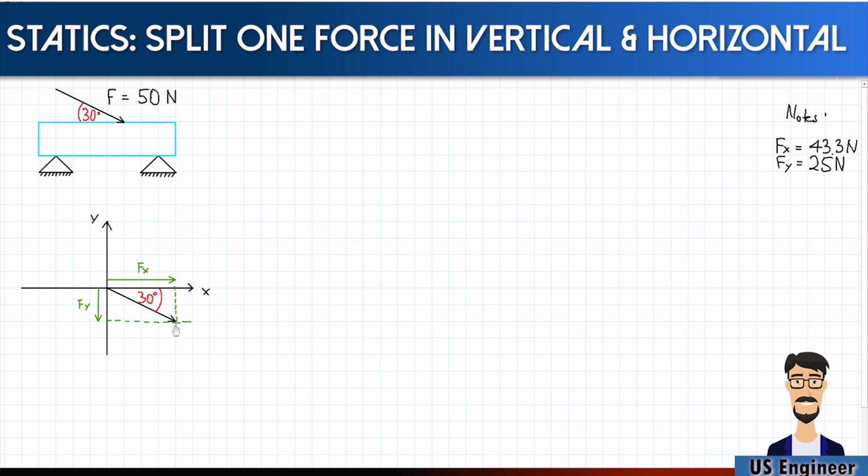Now, as I said before, there is a geometric and a mathematical approach to computing the magnitudes of the force vectors. Let's start with the geometric approach, and that approach involves drawing the force vectors true to scale. In other words, you need to make sure that the length of the force vectors reflect their magnitudes.